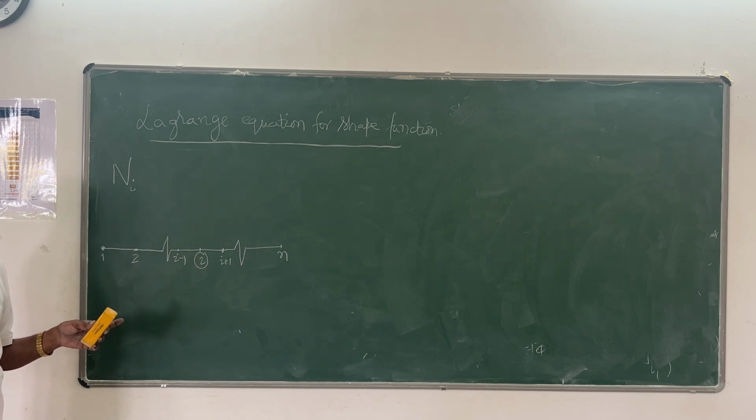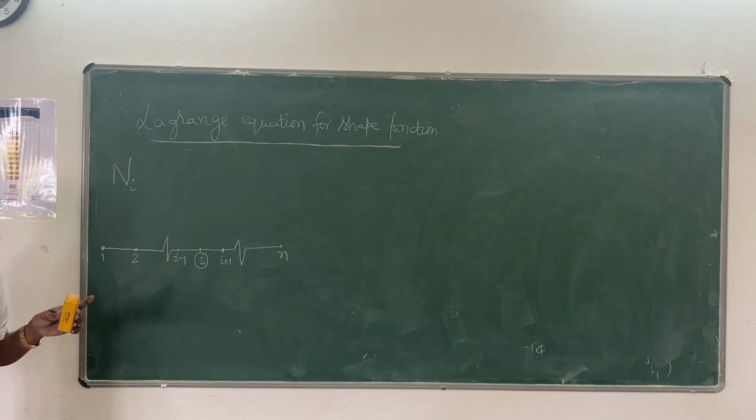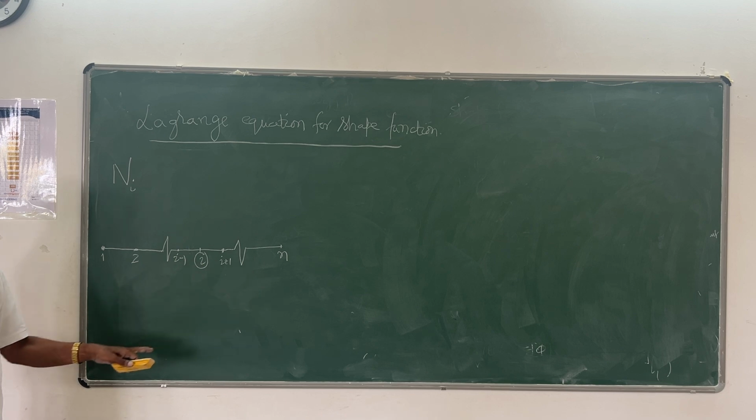That's only for isoparametric element theory. The relationship between natural coordinates and global Cartesian coordinates is only through the Jacobian, so you have to apply Jacobian transformations.